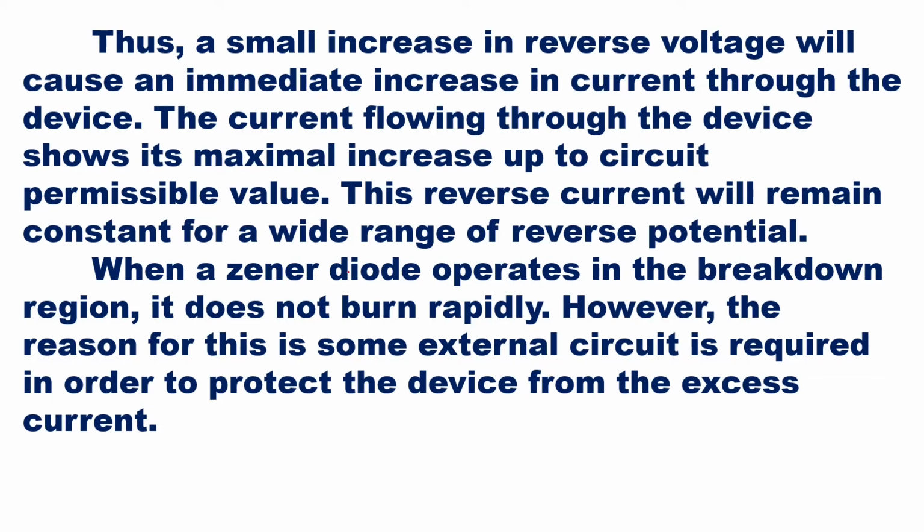The Zener diode is used in the area where it goes under reverse breakdown, where the voltage remains constant but the current goes on increasing. This is the specialty. The current can vary high and low, but the voltage remains constant. And this specialty of the Zener diode makes it a very useful device for circuits like voltage regulators.